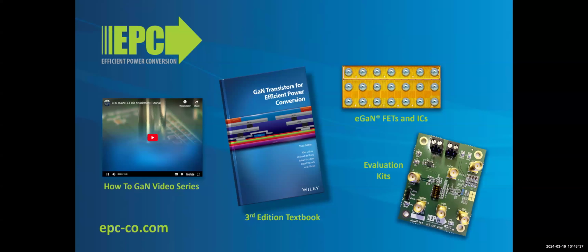So the thing that I said during the presentation is that we have a different approach between, let's say, typical converters and motor drive inverters. The typical converters, AC/DC, DC/DC converters, we're using GaN-FET. We usually tend to go as fast as possible to minimize the switching dissipation from the devices. In that case, there's not the problem of winding isolation.